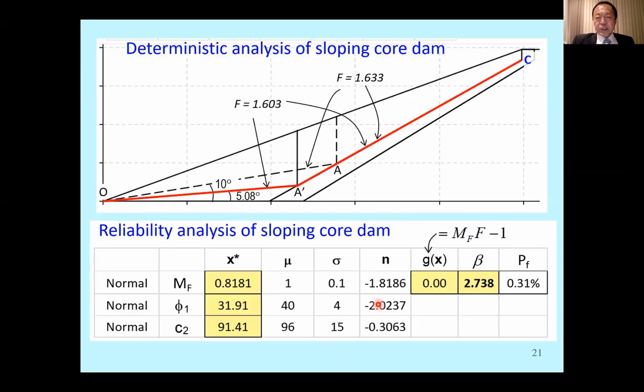By the way, this is adequate reliability and the probability of failure is adequately low. So this is a satisfactory situation for the mean value and standard deviation. Mean value is based on the Lam and Whitman mean value. For standard deviation, I took some typical coefficient of variation.